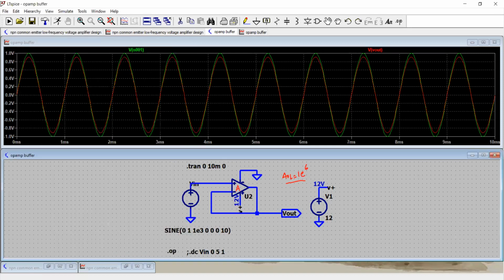We'll calculate that. Because you are using an op-amp, so it's an amplifier, so it has a frequency response from the Bode plot like this. So this is your, let's say, gain. This is your frequency, and this is about your minus 3 dB point, from where the gain starts dropping like minus 20 dB per decade.